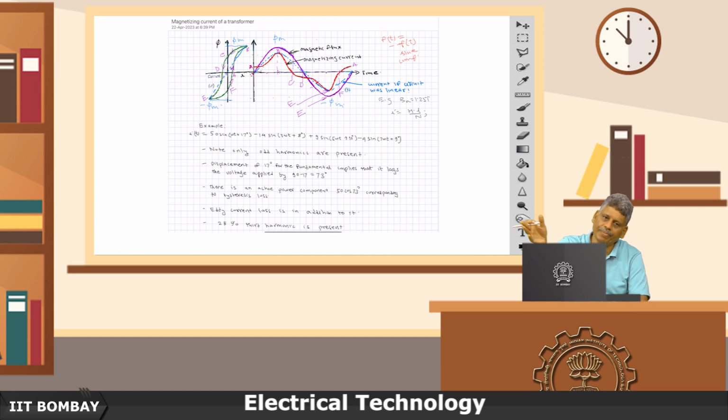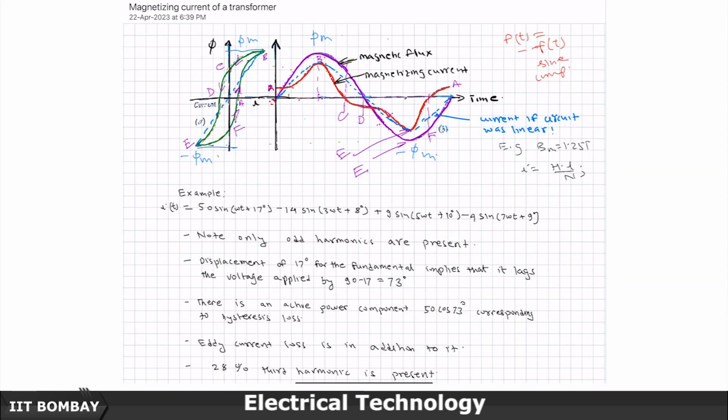So, the amplitudes of the harmonic levels decrease. Qualitatively, I will explain it like this: my dominant nature is, even though I have a nonlinearity, the nonlinearity is only a small deviation from sinusoid. So, the dominant thing will always be at the fundamental, but when I draw that something at fundamental, it will not properly depict this.